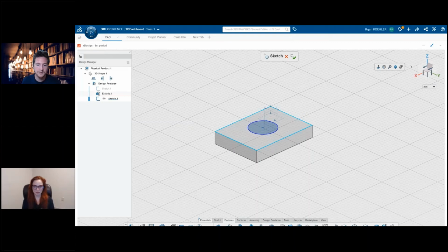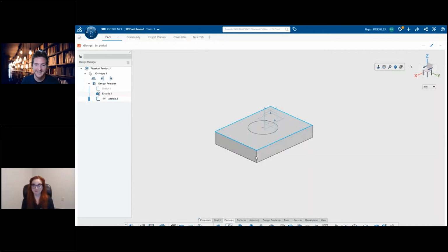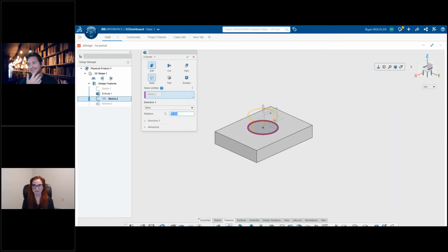Now, if a student wants to create an extrude, for those of you teachers out there, or we want to do an extrude cut, how many times do they actually click on extrude by accident? And then they create the feature after, and then you're like, oh, we got to delete that feature and redo it. Well, this is creating extrude right now, but if I take a look here, I can actually just swap to cut in the same menu.